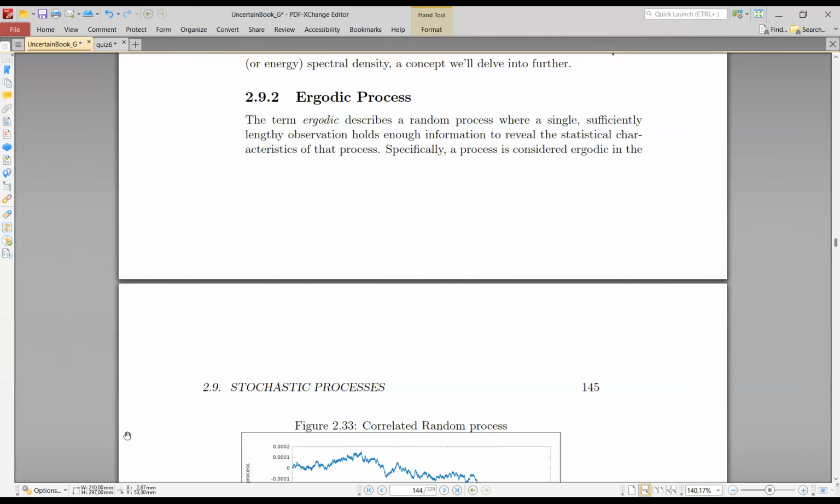out of this 10 minutes, you compute the mean and the variance. Then you can say that this is the real mean and this is the real variance of this white noise. Even if you take 100 years of measurement, it will be the same mean and the same variance. If you come tomorrow, or if you take the white noise from this resistor or that resistor or any other resistor, it will have the same statistics. So now we need to think differently: we are not talking about the real signal. The actual signal is random.